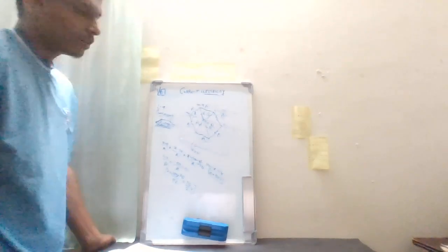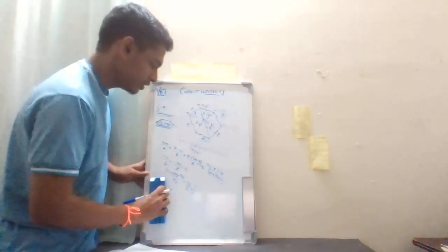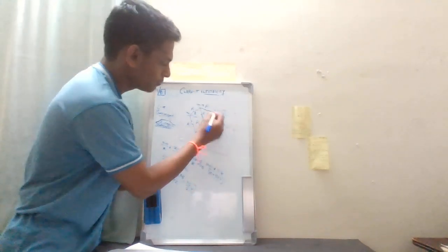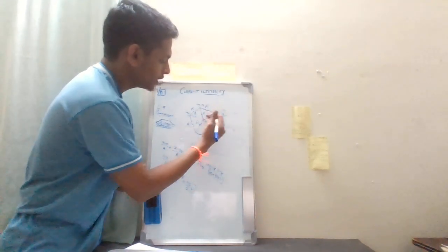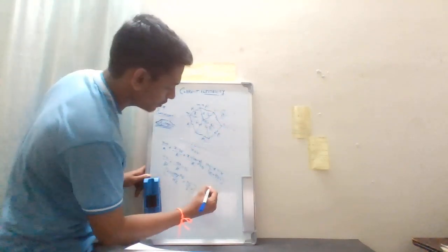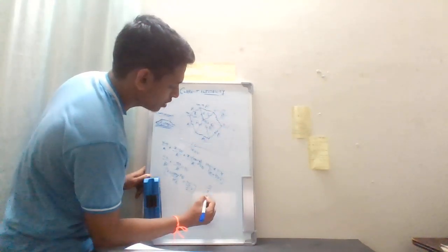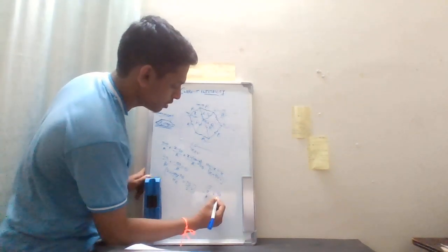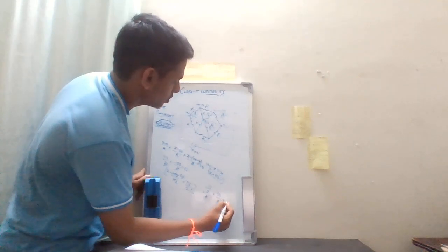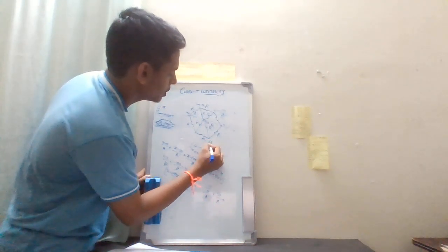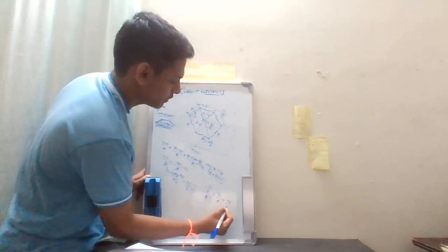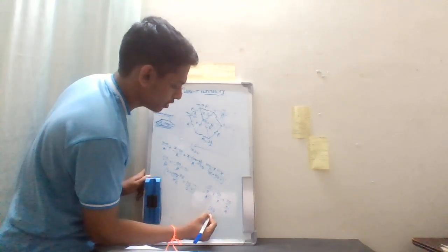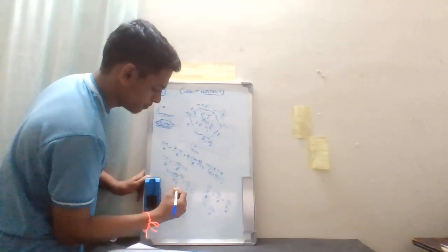Let's again apply KCL here. So that would be here I would exit, right? So the potential difference across this divided by R: 75 by 2 by R plus 50 minus 0 plus this will also be x. So 75 by 2, 75 by 2, 75 by 2 would be 75. So that would be 125 by R. This is I.